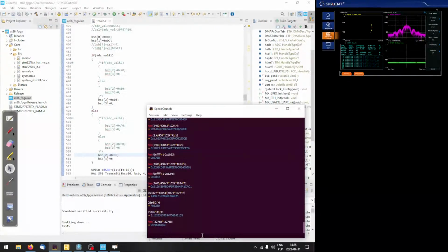So we've got values from 0 to 1023, meaning that for an angle of 0, we have to use a value of 0. And for an angle of pi over 2, which is 90 degrees, we have to use a value of 1024 divided by 4, 256. So that should be the value to use for plus 90 degrees phase shift.